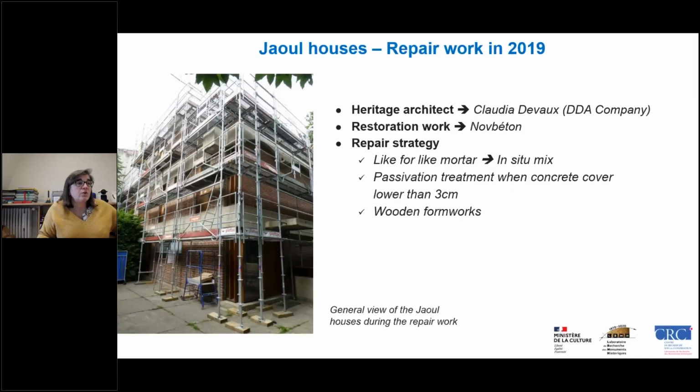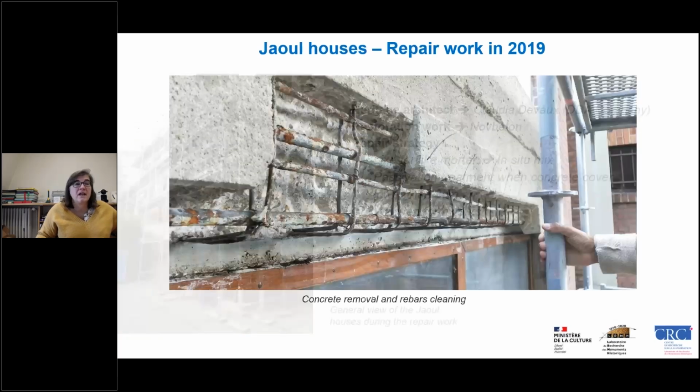So the restoration work was performed by the company Neuf Béton, and the repair strategy was to perform like-for-like mortar with an in-situ mix design. The passivation treatment was applied only when the concrete cover was lower than 3 centimeters, and again, wooden formwork was applied. And here you can see the concrete removal and the rebars cleaning.